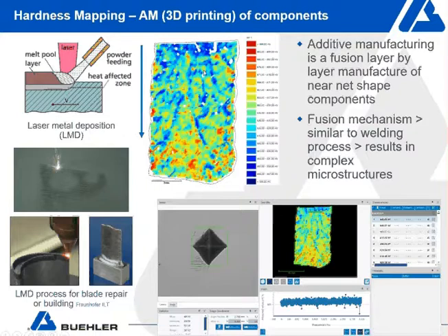And basically, you can hardness map that surface, and it will give you an indication where you still have high hardness that might be potentially regions for crack development. And this is why you can mitigate this in additive manufacturing if you have a bed that is heated up, so you're always exposing your component to high temperature to minimize stress development within the component.